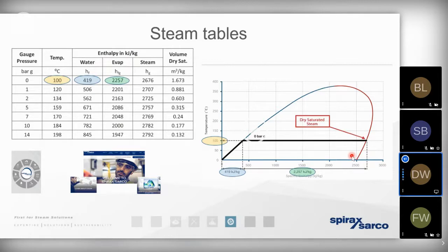So for example, if we've got a process that requires 9,800 kilograms per hour of steam, we're generating 10,000 kilograms per hour of steam in the boiler. But if we're losing 300 or 400 kilograms of steam, if it's giving up its energy to the distribution pipework and condensing, then we're at risk that we're not going to have enough steam to satisfy the process. The heat exchange rate could extend and extend, causing a problem with the process, or it could well be that we simply fail to hit the required target temperature altogether.